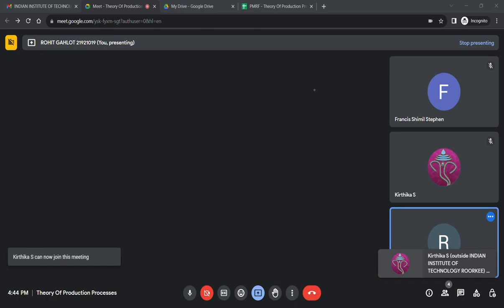So from here we can write the T solidification of the riser as K times the square of V by A. It is given as 2, and this is also... so what did I do? This is not the K. One second, let me check. The exponent is to be taken as 2. Okay, so this is N, not K.